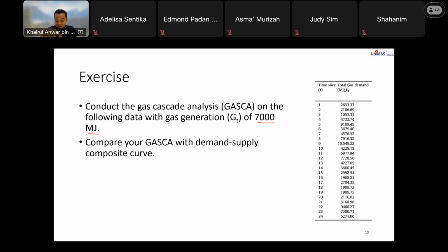That one you can refer to table 6. Then you recalculate QT equal to QT minus 1 plus CT plus DT. Then you will get the pinch, the largest negative value in all the cumulative energy. And you will see the Q naught and Q final are the same.